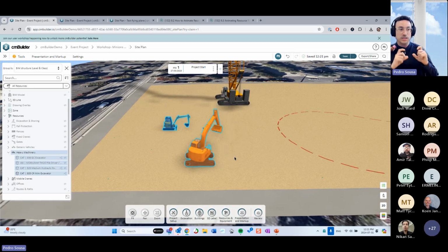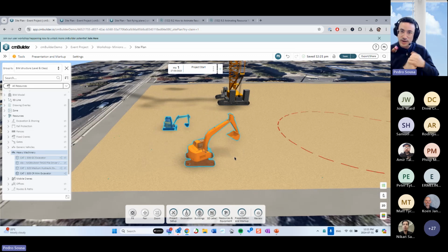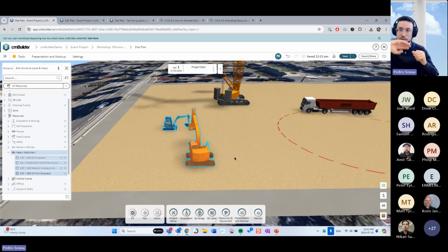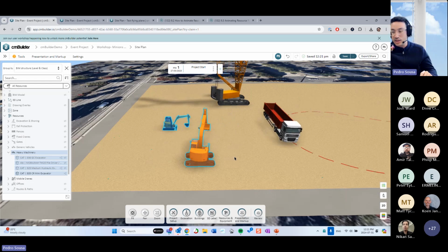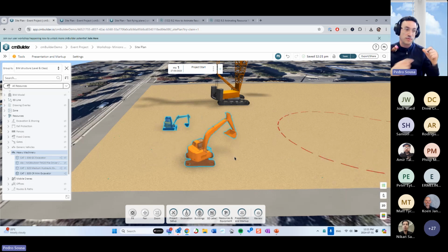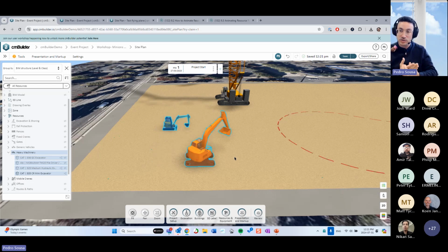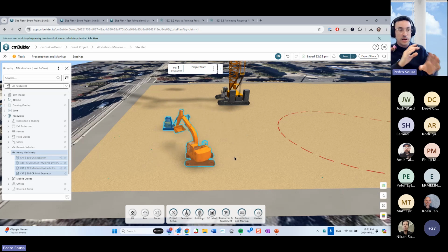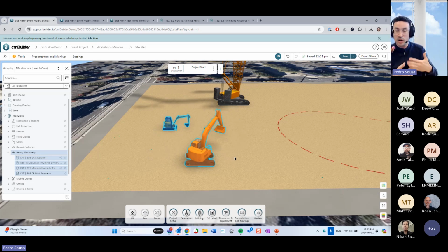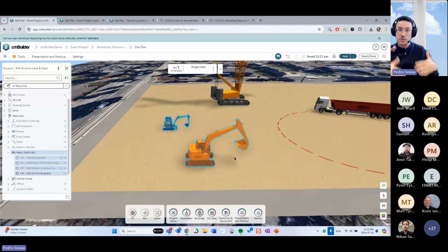Why am I saying that? It's because if you connect a scenario start trigger to an animation and then you have that object showing up on milestone 5, keep in mind that your animation will start the moment that you open the scenario. If you need that animation to really start on milestone 5, there is a way for us to do that. But if you connect it to the scenario start, regardless of whether the object is there or not on that milestone, the animation will still be playing.